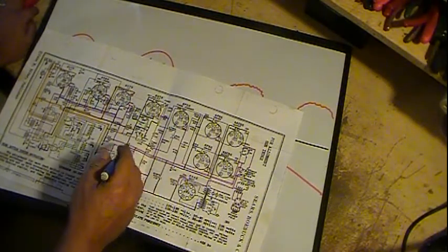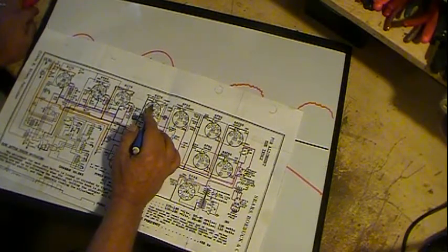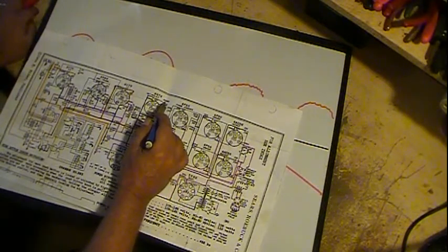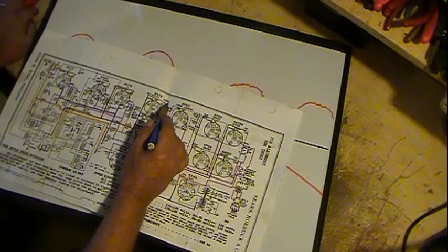And then, coming out of that plate, our signal, we run it through a cap. And this is ground right here on the cathode. This black shows ground, goes down to ground here. At this point, 0.00025 microfarad cap right there is my last little filter.